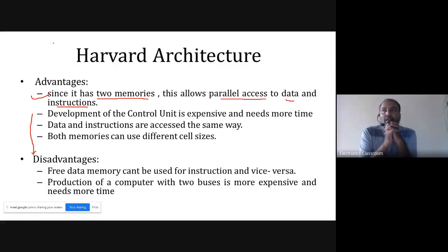For example, in the 8085 microprocessor, we have MOV instructions as well as LHLD and LXI H. So data transfer instructions between registers as well as data transfer instructions related to memory operations are both the same type of operation, but the instruction or access format was different.